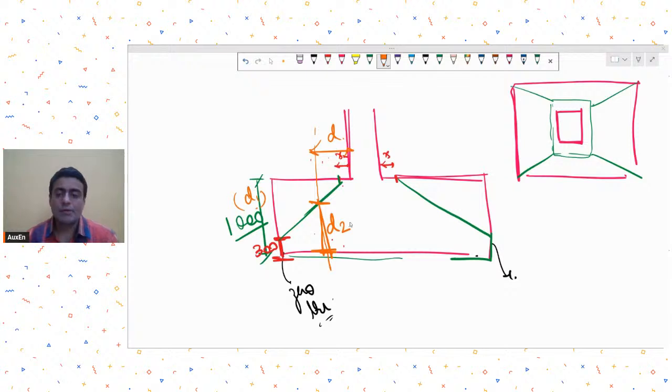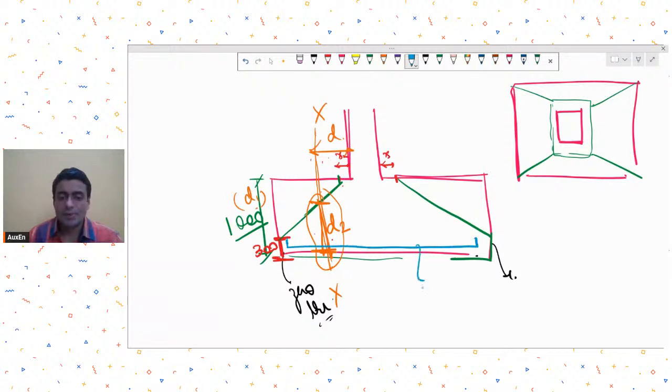So now when you want to check the one-way shear, you should be able to ensure that this thickness D2 is safe to take this one-way shear at this section XX, let's say. All right. For this, what one trick designers use, that let's say you have provided reinforcement over here. Okay. So suppose you provided 12 at 150 as your tension reinforcement. Now this tension reinforcement 12 at 150, if I were to calculate PT at this section, let's call it section 1, and if I were to calculate the